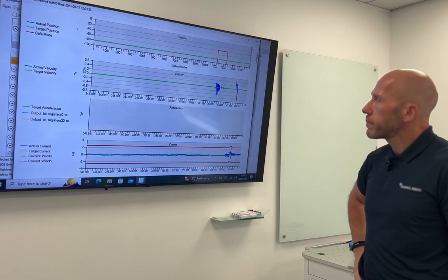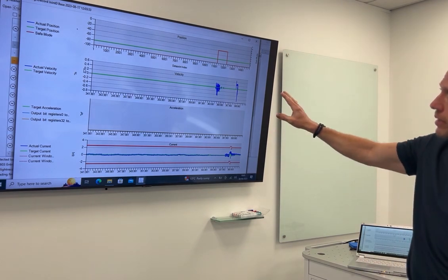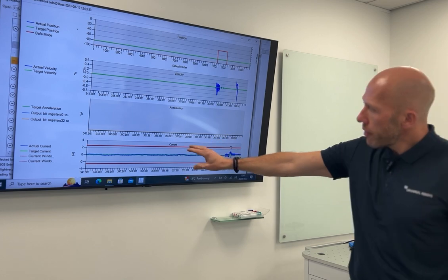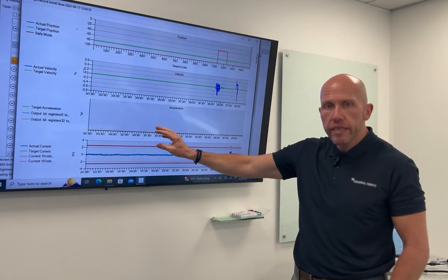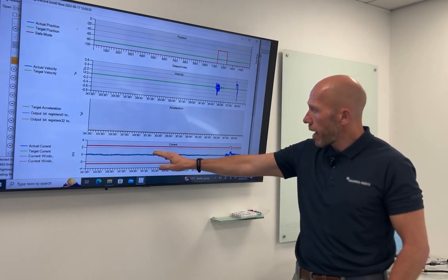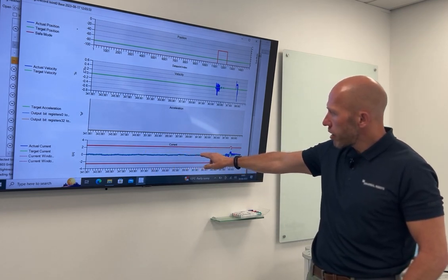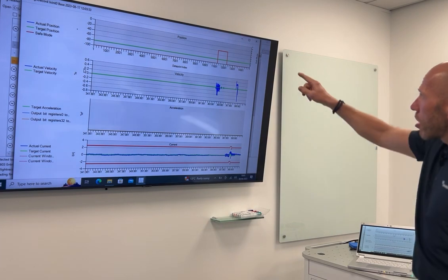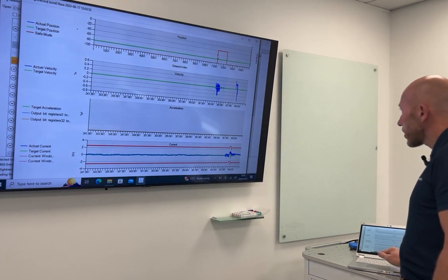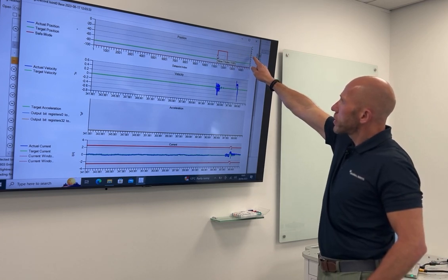just loads that. So here we can see the actual positions of the robot, the safe mode, and these are critical graphs at the bottom. These are actual and target currents, so we're looking at these to see if they match. We can see there's nothing wrong there. But we can see an error up here, which is error number 7. So it's errored out on line number 7.